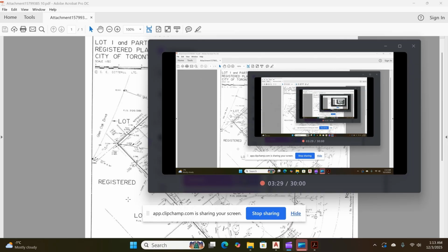For curved segments, additional information such as arc length, chord length, bearing reference, and radius is required. It is important to review and interpret this information carefully before entering any data into the drawing environment.